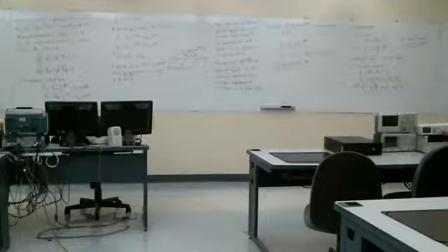These are waves where the wavelength is related to the propagation constant. It's just 2 pi over beta. So that's the wavelength. And then the phase velocity, the rate at which the phase fronts are propagating outward, is equal to omega divided by beta.